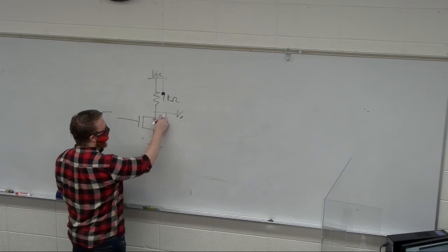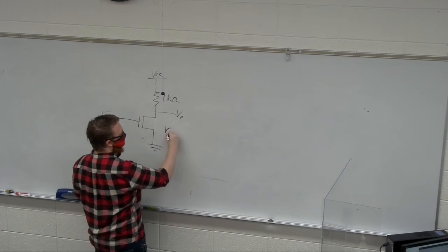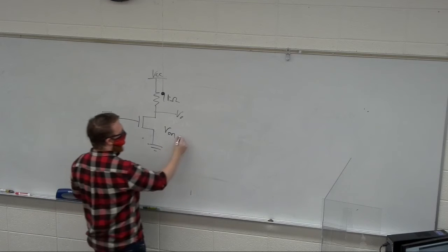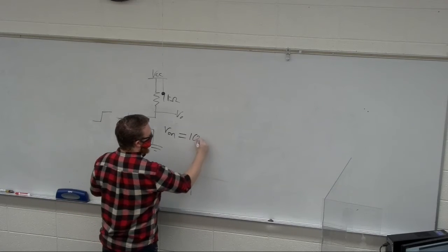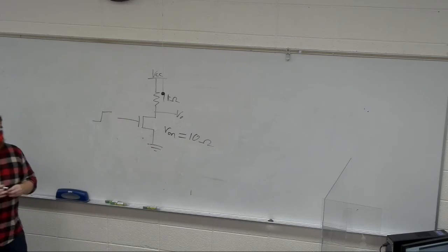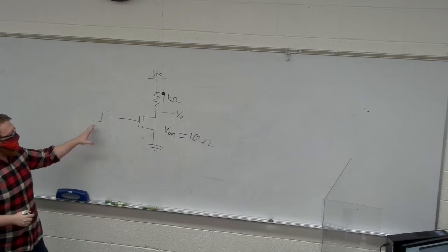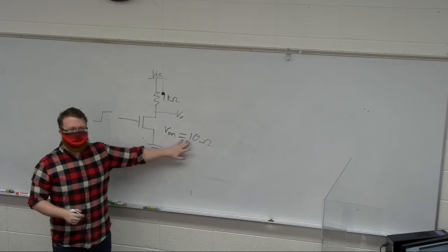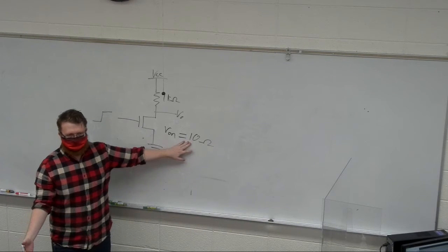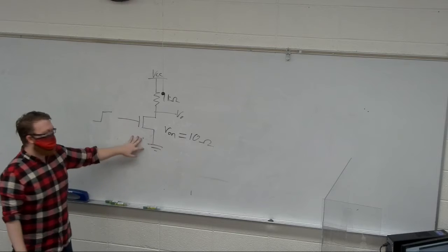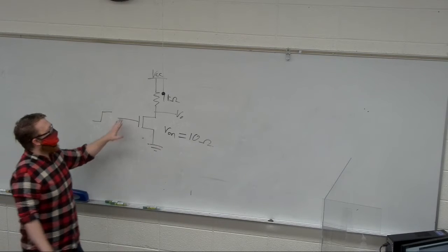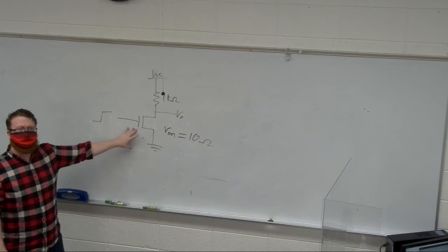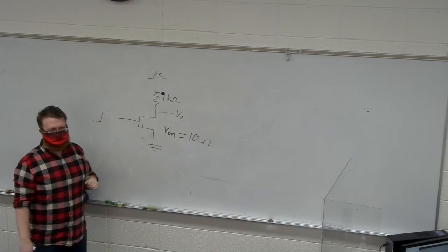Now let's say that on my switch, we have this term called R on, which is the resistance for the switch being on. And say the R on is 10 ohms. So what that means is that when I pull to 0, it can do very quickly, because the bigger the resistance, the harder it is to make that transition. So this pulls to 0 very easily compared to pulling it back up to 1. So the de-assertion delay is actually going to be lower than the assertion delay.